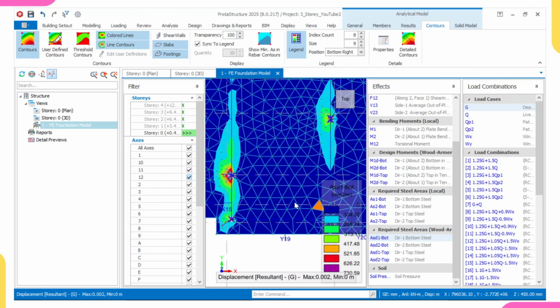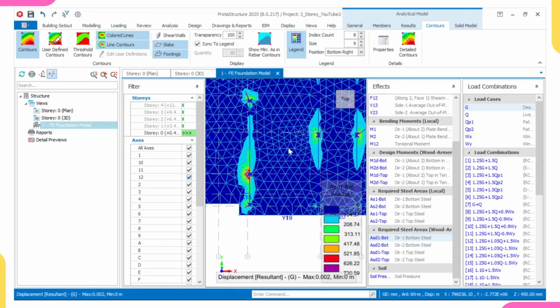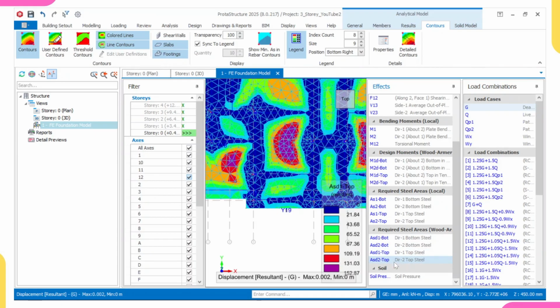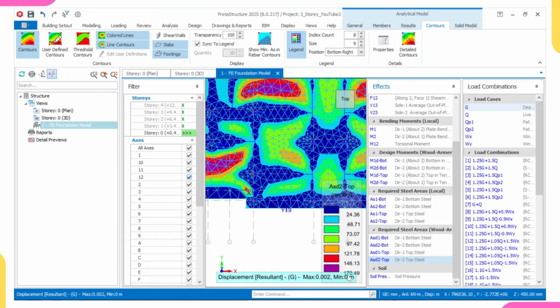So in this, you can use your steel table and provide reinforcement using this, or you can go with the one that the software gave you, any of them. So I'll also come over and load this. I'll click on this and load this. I will also load this. So the area of steel here is 170. So I will also come over to this soil pressure and also load this.